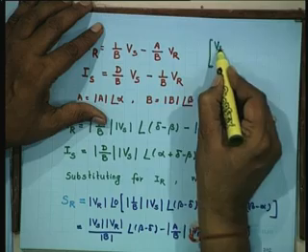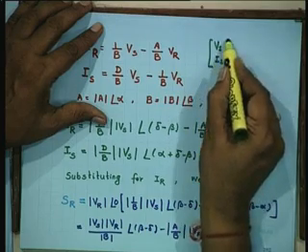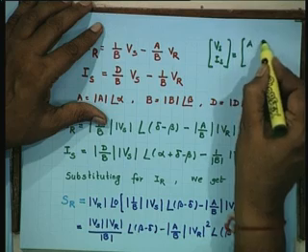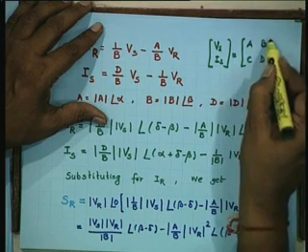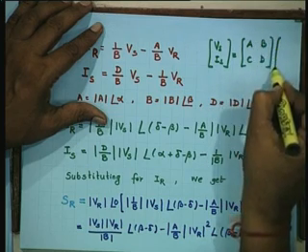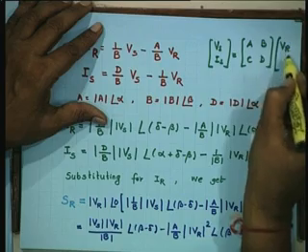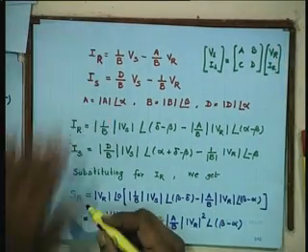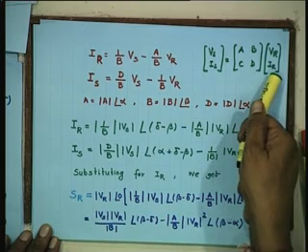If you recall your old equation, which is very important equation, I will rewrite here: Vs, Is equals the ABCD matrix times Vr, Ir. Find out Ir.